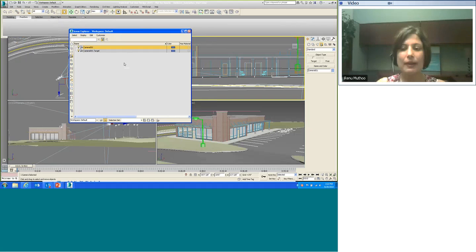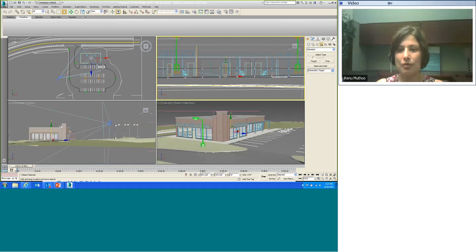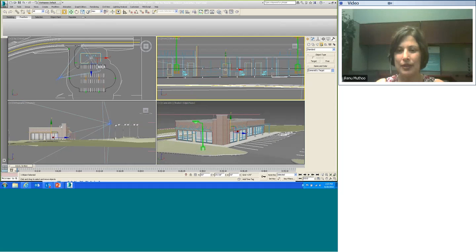So right now I want to move the target up. So I will select the target, and it automatically selects it in the viewport. So I don't need the Scene Explorer anymore, and today's focus is not on the Scene Explorer. So we will move back to our animation topic. So we will close the Scene Explorer and move the target slightly up. Now I think this looks like a good view for animating, and so we have moved our camera as well as we have moved our target up. So you can just see it in the camera viewport right here.